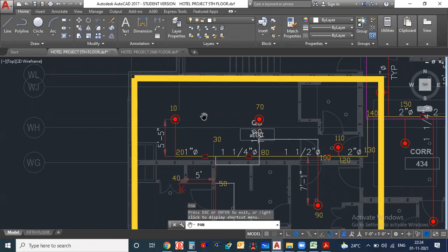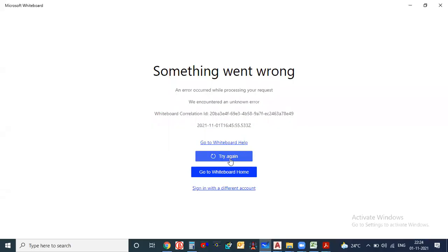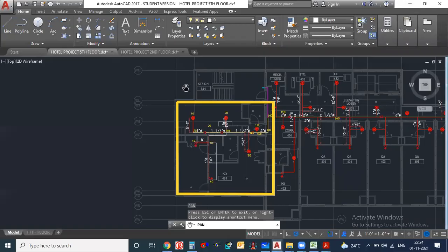How to compensate that? Try to add some fittings, but I think 10% is more than enough. If there are 30 fittings and in your calculation you are considering 33 or 35 fittings, nothing will happen. 10% is a very, very minimum value,